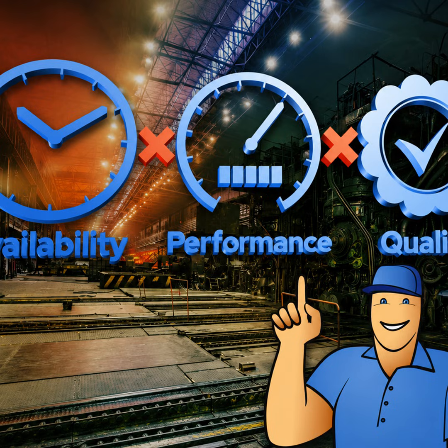Similarly, high-mix, low-volume operations will inherently have lower scores of around 60% because of routine, fairly constant changeovers and slow cycles. This will become clearer when we discuss the factors that go into calculating the KPI. Finally, continuous operations that run 24/7 should aim for and target 85% or more since they are maximizing capacity utilization.